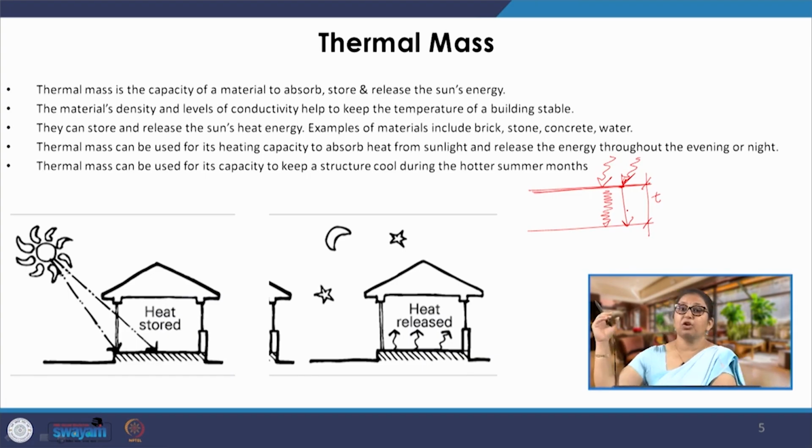If a lot of radiation is incident on that, even then the entire mass of the stone wall is not going to get heated up to a level where it becomes hotter than the indoor temperature and starts to transmit inside. The re-emission of that heat is only going to take place when the temperature here, the Ti, is lower than the temperature of this body, the Ts.